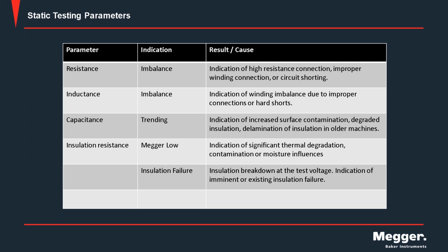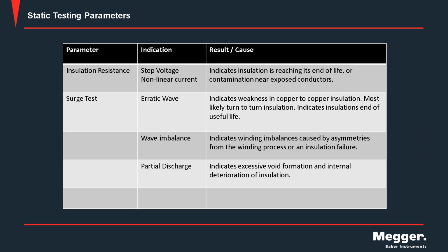And a lot of this testing can be performed from the switchgear. A majority of this testing actually can be performed from the switchgear. There are some rare exceptions. Of course, PD testing has to be done at the motor, but low voltage resistance, insulation resistance, step voltage, and surge testing can all be accomplished from the switchgear. So that's good, right? We don't have to disconnect a bunch of stuff to get to what we need to get to.